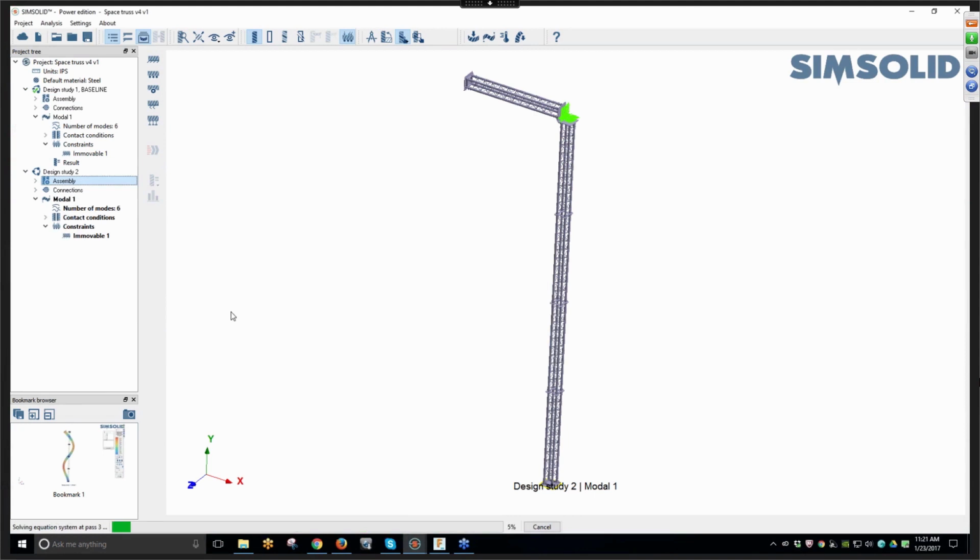And each one of those passes is increasing the quality of the results, correct? The quality, yes. It's like h-adaptive in FEA. You're solving it, and you can think of it as locally remeshed. We don't locally remesh, but we locally enrich the solution, and then solve it again and look at the errors.